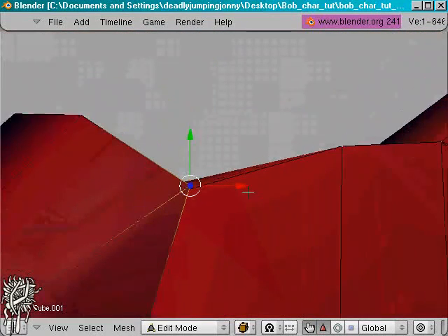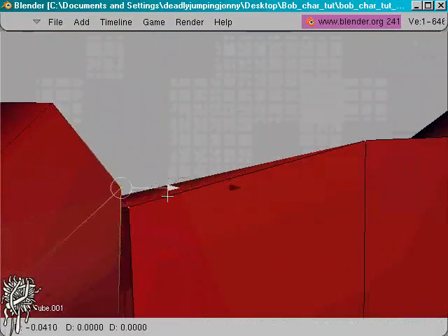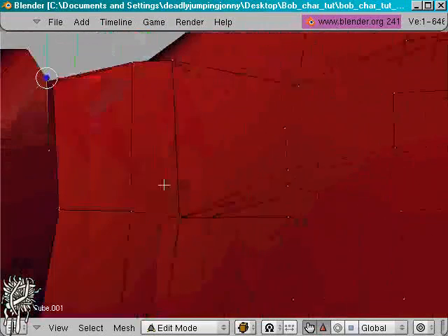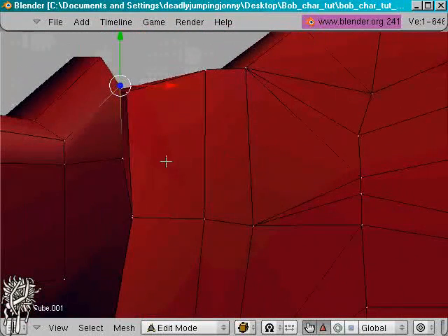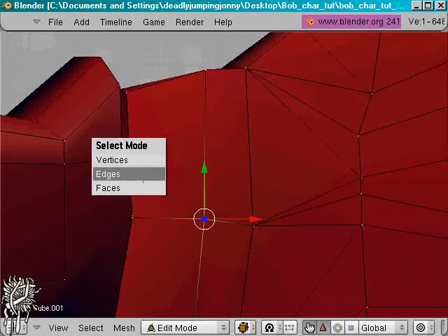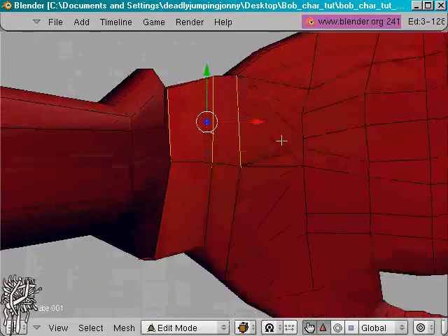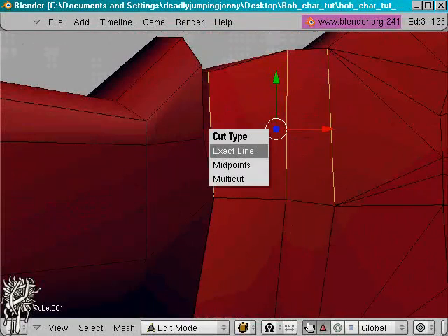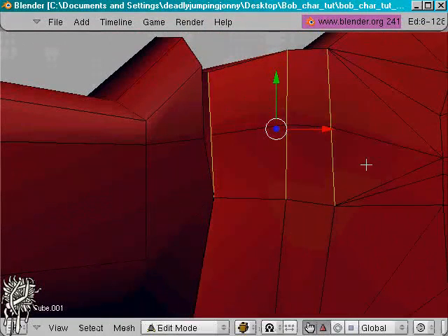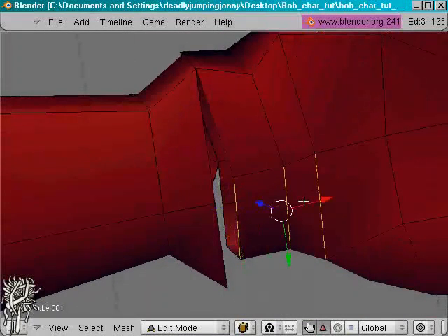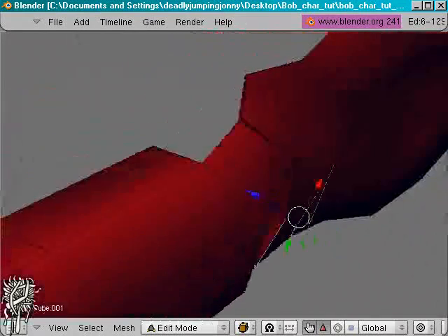See, I've misjudged the amount of vertices I'm going to need, which isn't that disastrous. We can just create some more. A little loop cut maybe. I'll just knife it again. Fairly simple. So we need 1, 2, and we're going to need the same on the bottom. So midpoints, knife. I'll do the same underneath. Midpoints, knife it. There we go. Yeah, there I've got enough vertices.